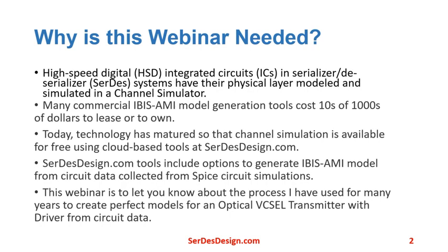Included with the SerDesDesign.com tools are options to generate IBIS-AMI models from circuit data collected from SPICE circuit simulations and hardware measurements. This webinar is to let you know about the process I have used for many years to create perfect models for an optical VCSEL transmitter with driver from circuit data.